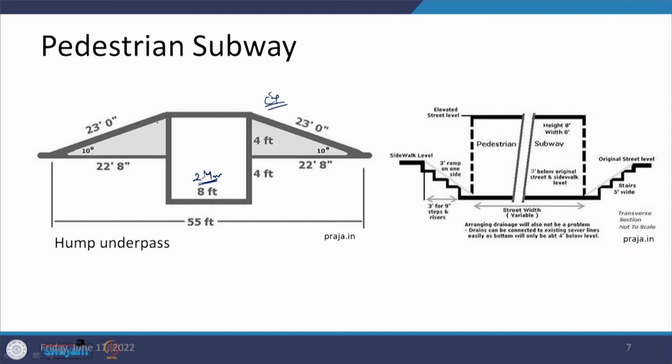And when we say that this is 1.5 meters and this is 1.25 meters, then accordingly if we are going as 1 in 30 here, this distance is going to be 45 meters on either side. So, the customizations can be done very easily in those forms.